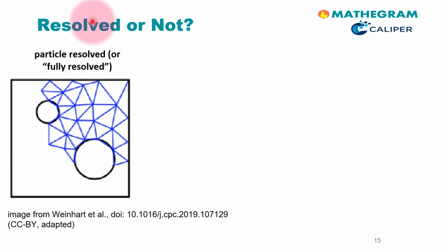In case we want to do this, we call this the particle resolved or fully resolved approach, which is nicely illustrated here in the figure provided by Weinhardt et al. As you can see, when following such an approach, the CFD mesh has to be finer than all the considered particles such that small-scale flow features are resolved. The force acting on the particles can then be directly evaluated from the stress and pressure field in the fluid.